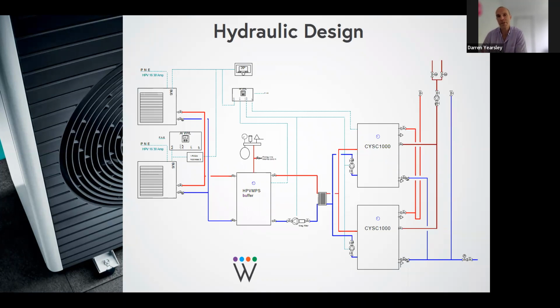Whenever your solar system is in production, if at all possible, you want to be running your hot water system in recovery mode. Because we've got this moving set point technology, if the system drops below 55 degrees, it doesn't matter whether the sun's shining or not, the system will recover the hot water. It takes energy from the building and recovers the hot water system. If the system senses that the solar system is in production and we're actually producing electricity, it will dynamically change the request in the cylinders up to 70 degrees to allow us to build energy and build hot water into the storage system. It's like an energy bank.